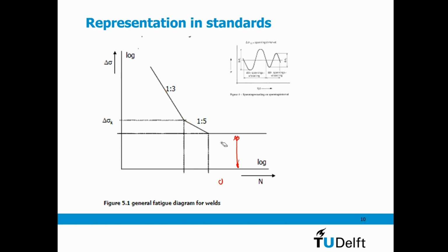If you see this curve, for example, you can also see that scaling of fatigue results becomes important. It becomes hard with yield stress and/or static stress checks. If I have a stress which is too high, and then I say, okay, I double my plate thickness, so the stress is halved. That does not mean that for yield that is then fairly easy to predict what happens.